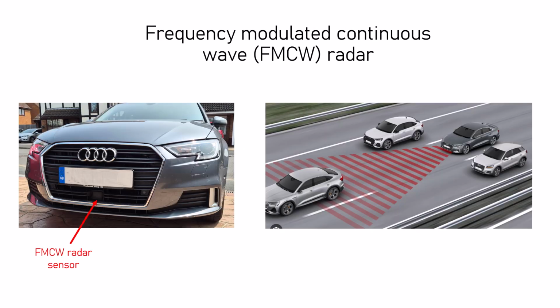Another type of continuous wave radar is frequency-modulated continuous wave, FMCW, radar. Whilst CW radar uses a constant frequency signal to detect targets which move, if the continuous signal is swept in frequency, the radar also becomes able to detect moving and stationary targets. This can lead to a very simple yet capable radar and is the technique used by automotive radars for adaptive cruise control and blind spot warning.